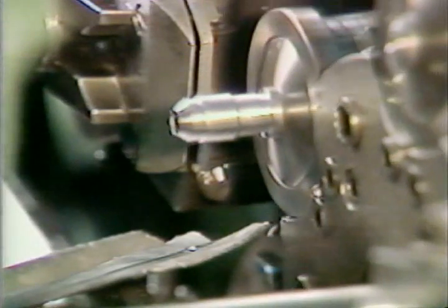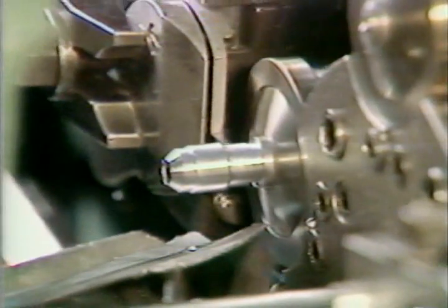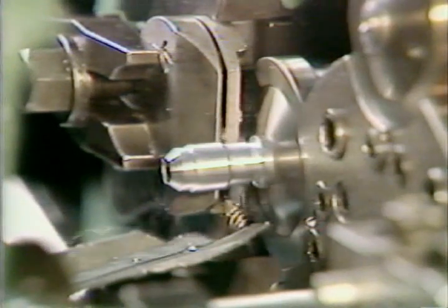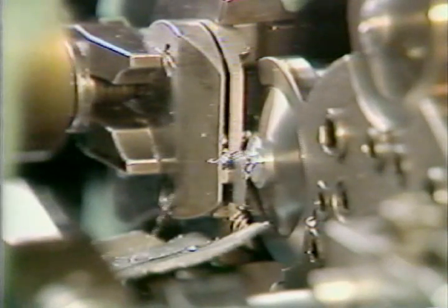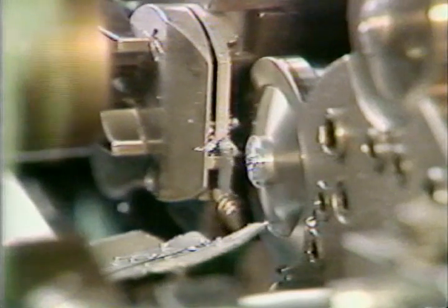Each cross slide arm will perform a different step in the forming of the part's outside dimensions. The fifth position tool swing arm moves the cutoff tool to cut off the finished part from the bar stock. The work chute carries the part away from the work area into some type of container.